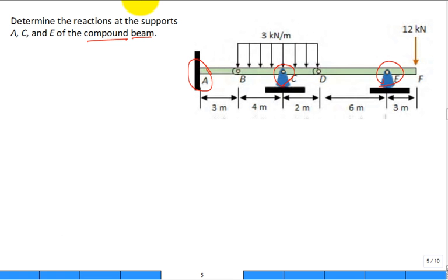All right, so let me go ahead and summarize. So at the support A, we have AX is a reaction unknown, AY is a reaction, and then we have the moments at A. This is like in the Z direction. Here is our X, here's our Y. What's coming out of the page? The Z. And so a lot of times we draw it like maybe this or that moment.